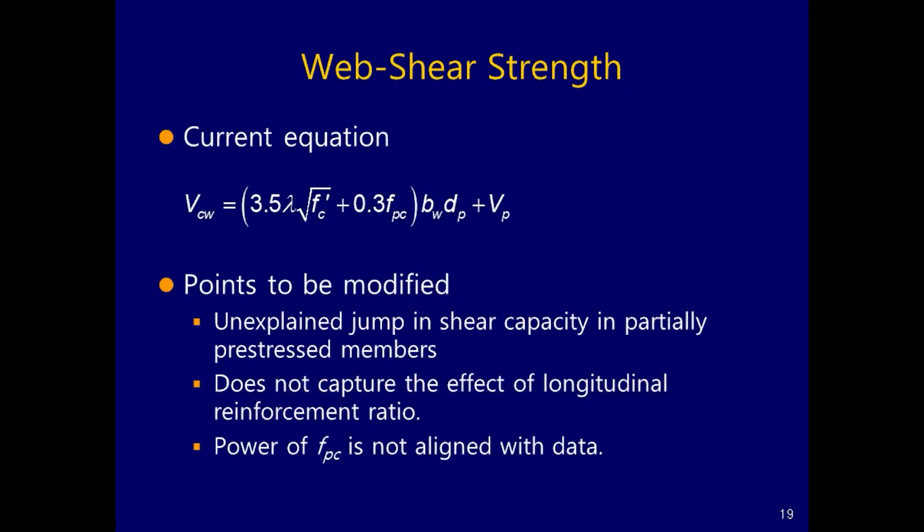How about web-shear strength, Vcw? This is the current equation, and points to be modified include unexplained jumping shear capacity in partially prestressed concrete members.